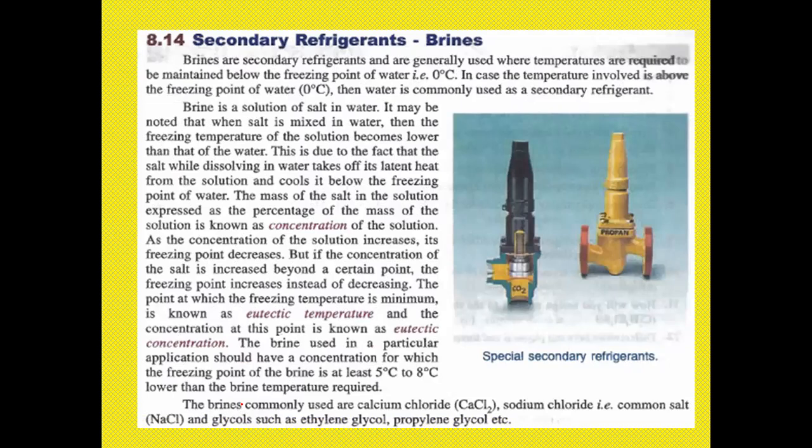Finally, the brines are the refrigerants used for maintaining low freezing points. In case the temperature involved is above the freezing point of water, then water is commonly used as the secondary refrigerant.